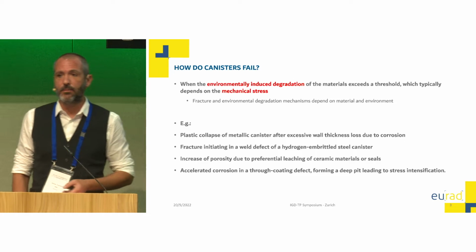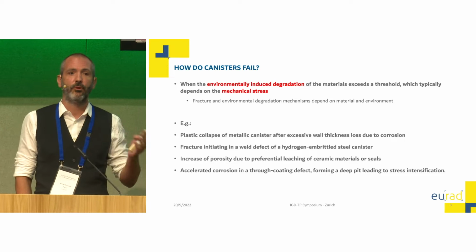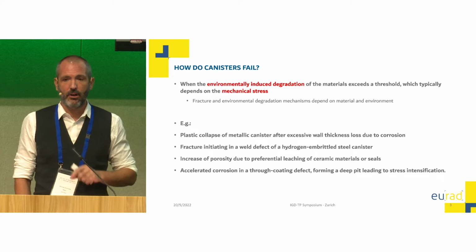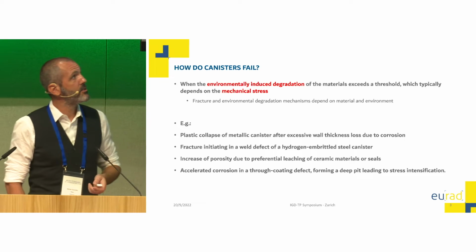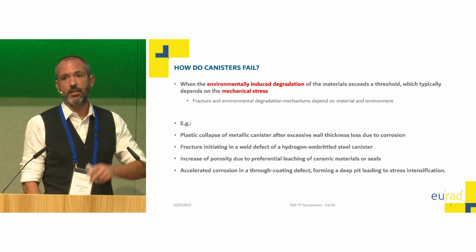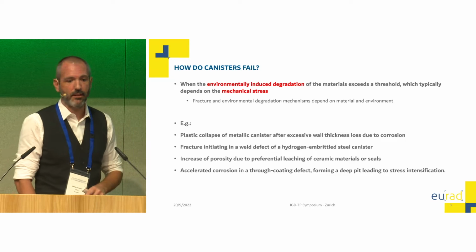And some examples here of, let's say, credible ways different canister concepts would eventually fail. So you have a nice metallic canister that corrodes uniformly, and its wall thickness gradually becomes smaller and smaller until it reaches a certain thickness that can no longer support the lithostatic stress, and the whole thing collapses plastically, right?